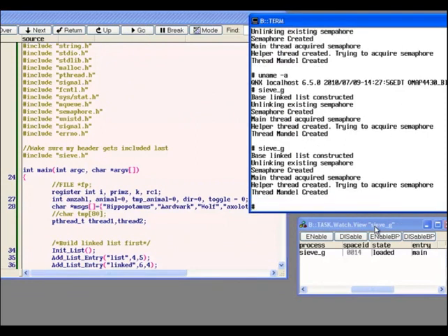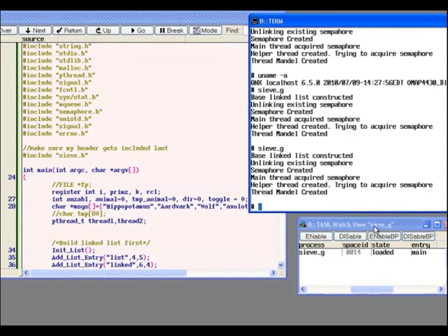So the watch system automatically takes care of reloading processes. But be aware that the watch system sets a breakpoint onto the kernel routine that actually loads the process and starts the process. So anytime you start a process, you will have a small break and go within the debugger, which may impact the runtime of your target.